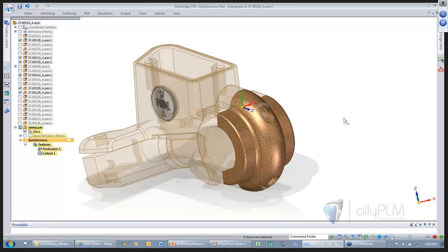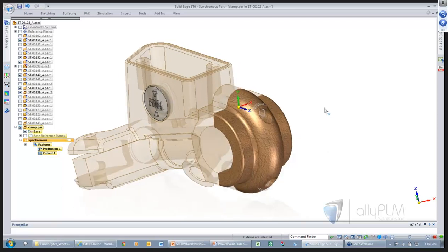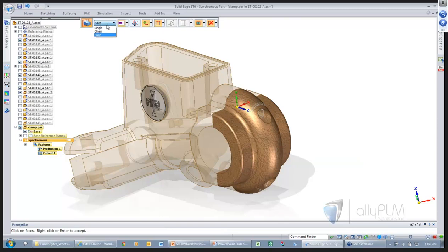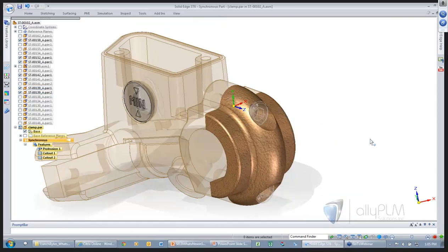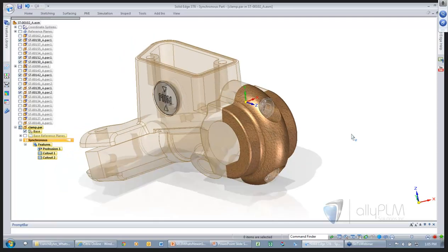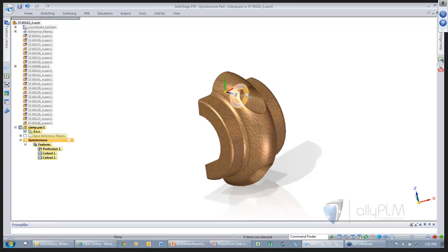These have the heads on them, so I need to create more of a counterbore shape. I'm going to come back to an extrude and take that a step farther with ST6. I can grab chain and actually grab the edges of those fasteners. So instead of coming in there and doing include, I picked the geometry directly and extruded it out. Let me hide the previous level. Now here it's just referencing shape and extrude or cut. So these are kind of cutouts. I don't want to call them dumb cutouts, but you get the idea.